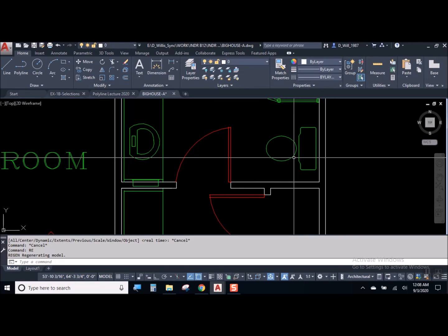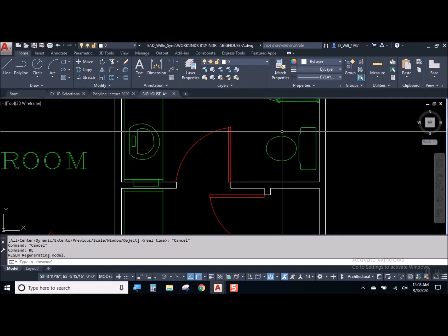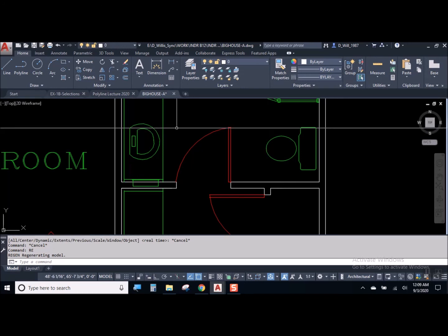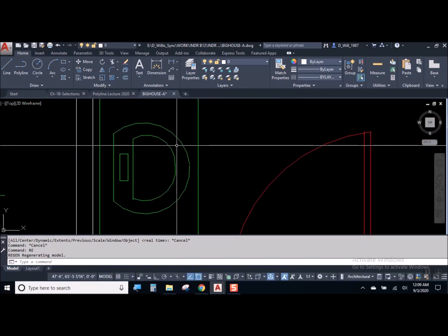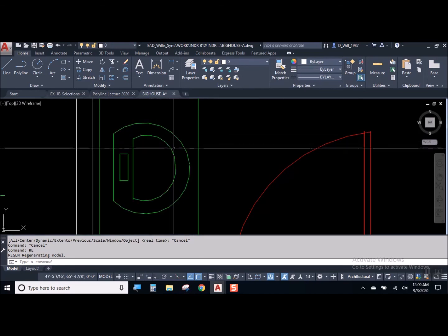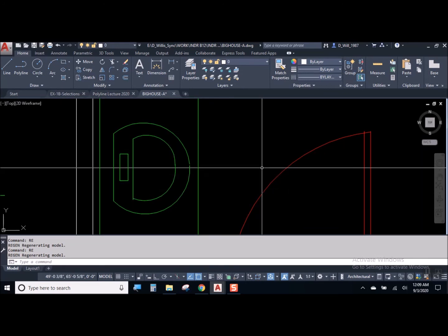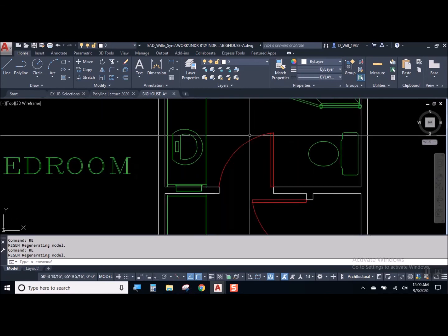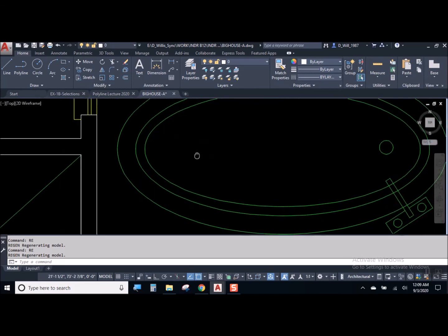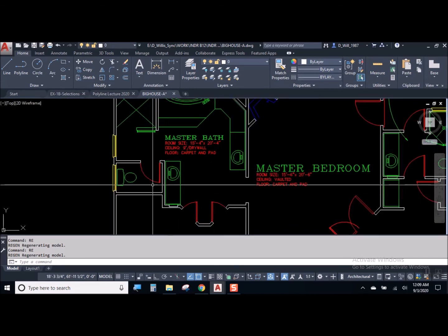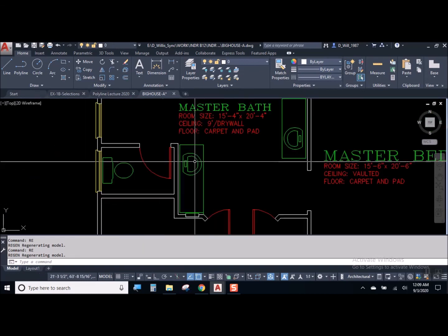Okay, with AutoCAD, you've got to remember it came out in 1982. Back then, RAM and memory were expensive and rare. So it does that to save a little bit of memory. Because technically, on a circle, how many edges does a circle have? Well, it has an infinite number of edges or points that make up the edge, but no computer is going to be able to manage an infinite number of anything. So we get this visual approximation on the screen. Even if it looks ratty on the screen, it will always print out nice and smooth and beautiful. So refreshing the screen is for you, and has nothing to do with the final printout.